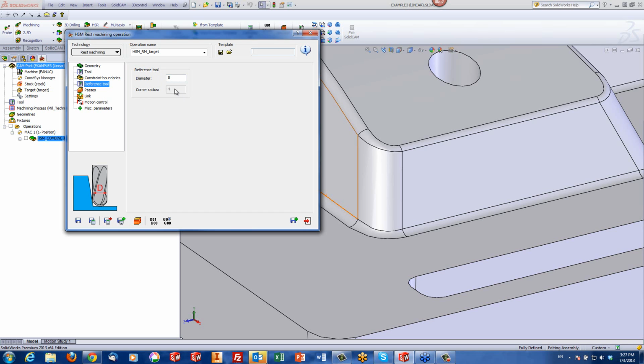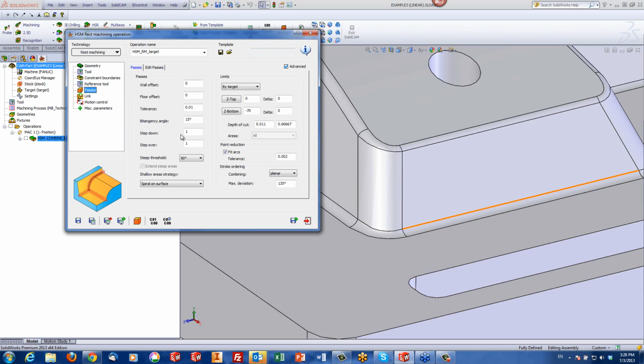So it'll work according to that 4 millimeter radius. Personally, I like to do a little more than what I wrote over here, say 9 millimeters, to give it a little bit of an overlap between where I was machined already and what I didn't machine. Let's go into our passes, and I'll set my passes at this point at every 0.2 millimeters.